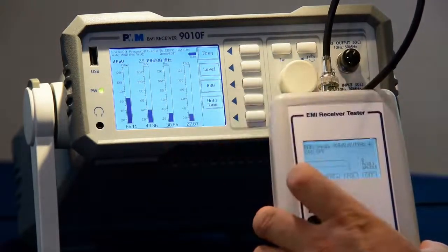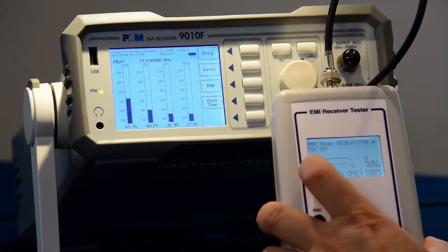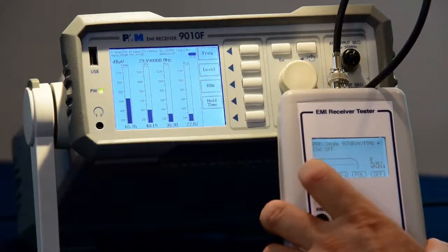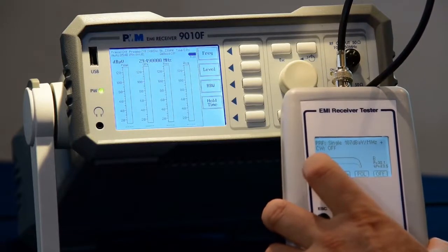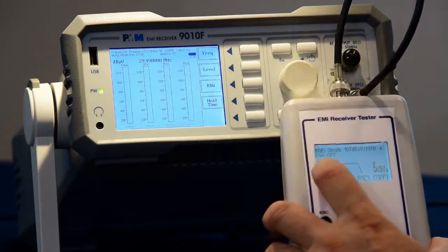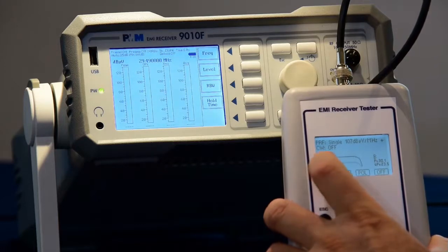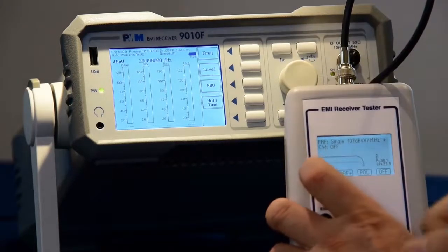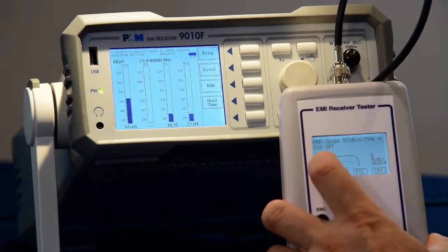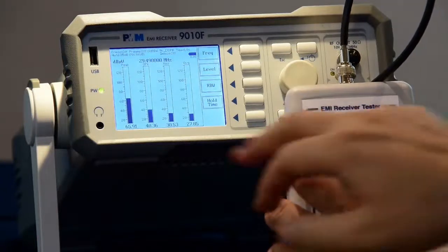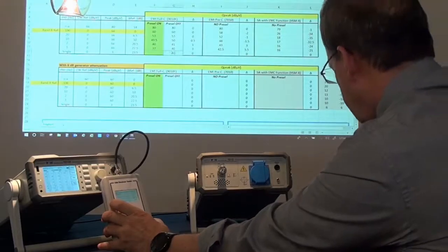We already have something there, it's almost 40, so we can push it some more, because depending on when this pulse is occurring, we then need to wait the whole time for the quasi-peak detector to charge and to measure, and then we can read what's happening. You see now we cannot see it immediately, now it is there. So we keep pushing some time just to keep the level constant, and you see it's about 40, so we can write it here: 40.